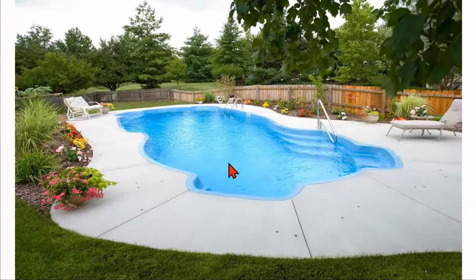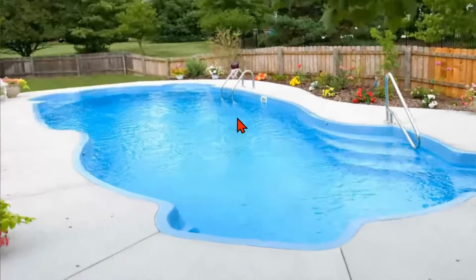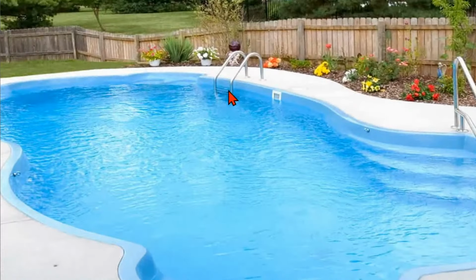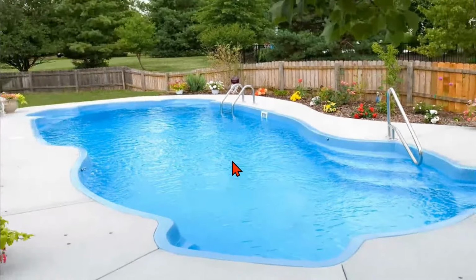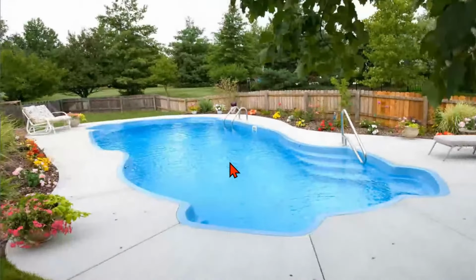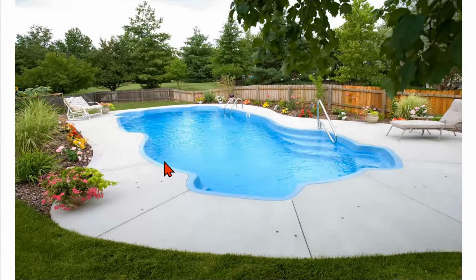Well, I'm sure we have another picture of that pool. There you go, right there. And hopefully that handrail, there you go, it's in the water. So we should be done. Good to go there. Nothing else. Don't let somebody tell you now you've got to go and try to bond the water. It's done right here, as long as this rail is connected to the equipotential bonding grid, and it should be. And it's required to. So we shouldn't have any problem with that. Okay, all right. Do we have any more?